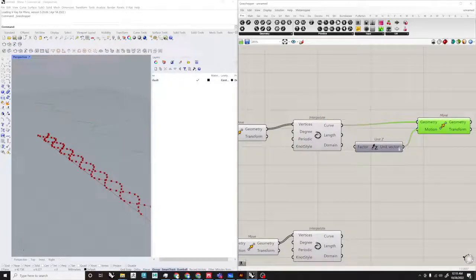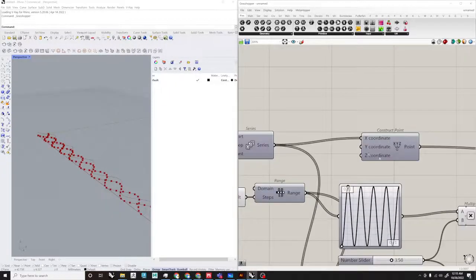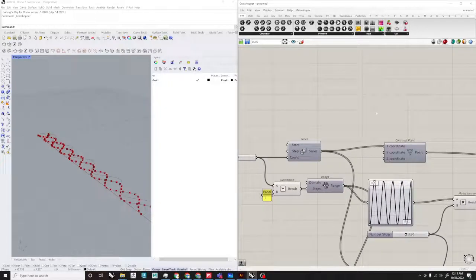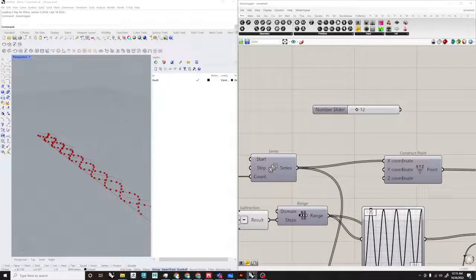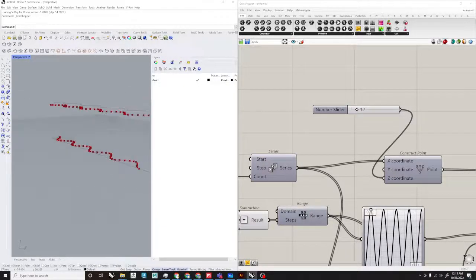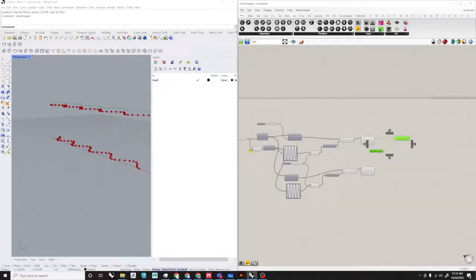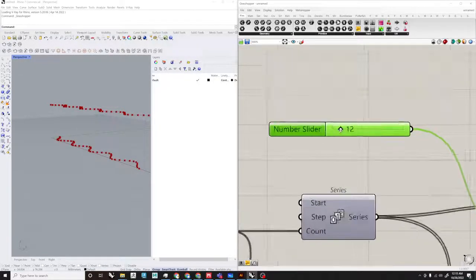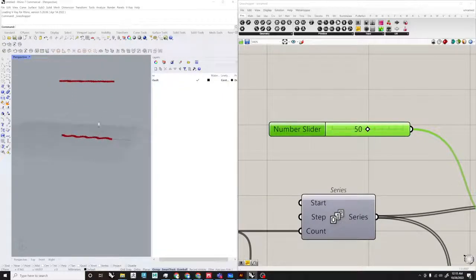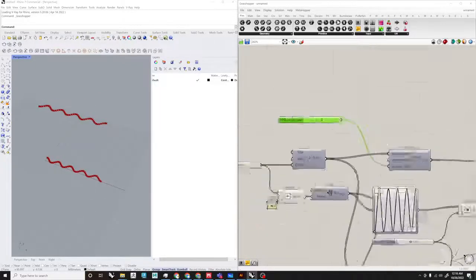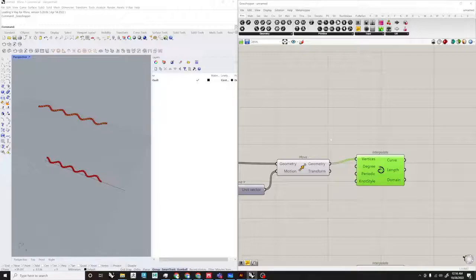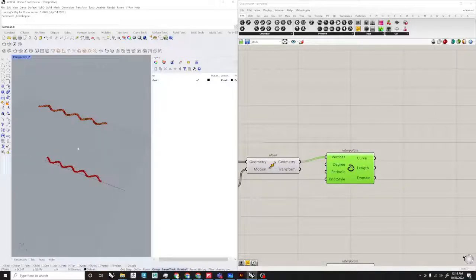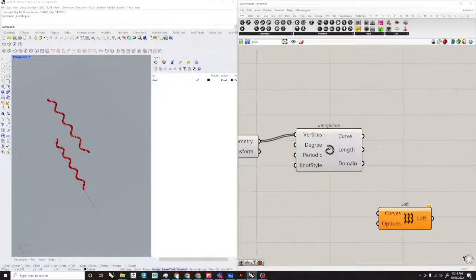So we'll move this in the Z direction. Technically, you can also construct a point at the coordinate you want. I think you can just do that. I could be wrong. Oh, yeah, you can. Okay. Technically, we don't even need to do this, but it's intuitive as well. So this will give me the height, so we'll say 50 as well. Of course, it's 50 millimeters, so it's pretty small, but we are just working with theoretically unitless, but we have millimeters defaulted right now. And then let's just try this real quick. I just want to loft and show you guys what the surface looks like.